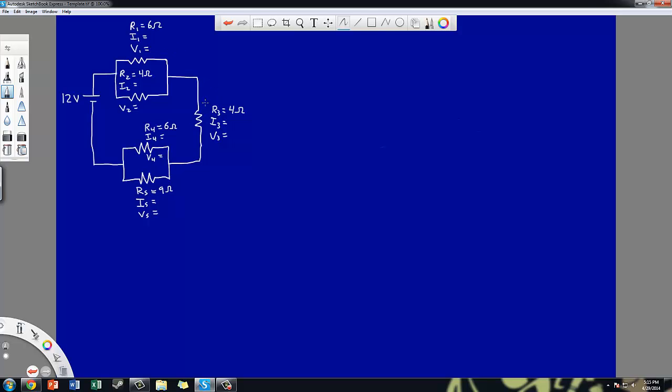As you get a little bit better at viewing these circuits, certain types of visual cues kind of stand out. For instance, the fact that there's a box right here tells me that something's going on with parallel because we have a pathway that's splitting. Similarly, the fact that this one is all on its own tells me that it's probably going to get incorporated through series, and then same thing with the box idea down here.